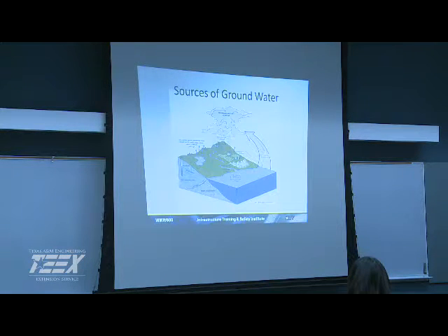So brackish water is important, especially in areas dealing with a lot of drought conditions: Texas, Arizona, New Mexico, a lot of those places, especially West Texas. West Texas has already got it going. They're doing toilet to tap. They're taking the discharge from their wastewater treatment facilities, running it through an RO process, and blending it back in with their raw water, and then it's going back through a treatment process for each of the small cities.